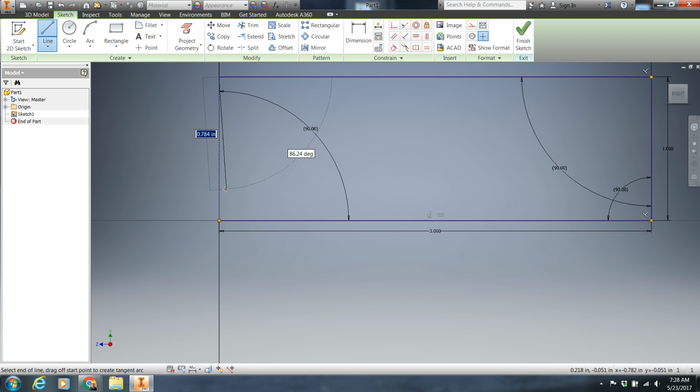Even though right now a lot of them are 90, it will not always be 90. You could click, which is fine, but it's not always precise. I do not recommend it. So I'll type in 1, then I'll hit Tab again. It's about where I want. I see it's 84, which is close again to 90. I'll type in 90, and I'll hit enter. To get out of that, I'm going to press escape.